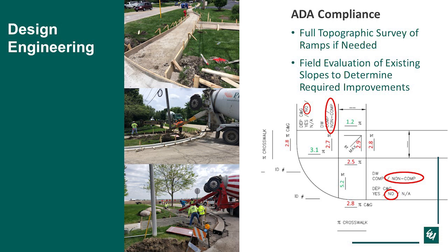Sometimes a full topographic survey is necessary because the area is steep or whatnot, and sometimes you'll have to put in curbs in order to make the ADA work, and sometimes you'll have to replace several squares back from the corners. So we do all that in design.